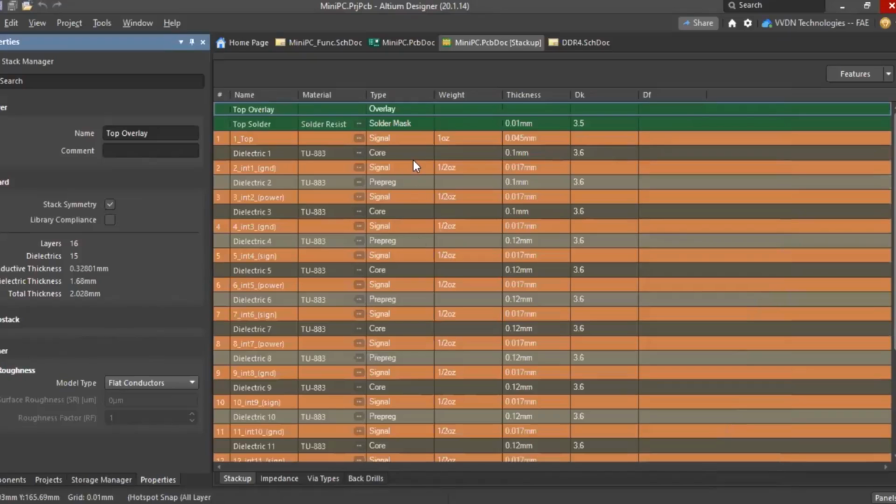I mean, it causes signal loss, or it affects the signal, right? So in that case, you can mention the roughness of the material conductor, and based on that, it gives the impedance. Because this roughness affects the impedance only. So next we will.